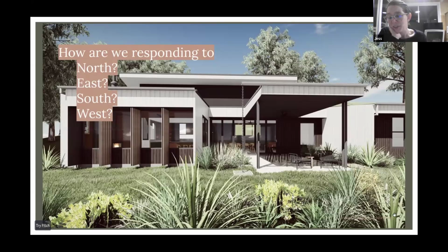And then on the south, that's where we get all of our beautiful sea breezes from, the southeast for us. And so on the south, that does also mean that we tend to get wind-driven rain. So we want to have eaves on the south, while we don't get any sun. We do often get wind-driven rain, so we do usually look to protect our south-facing windows with some roof overhangs so that we don't have to shut them as soon as it starts raining. Yeah, so that's a little overview. Amazing. Well thought out.